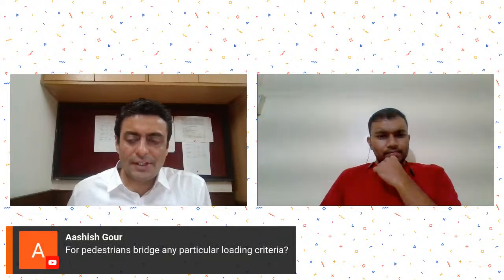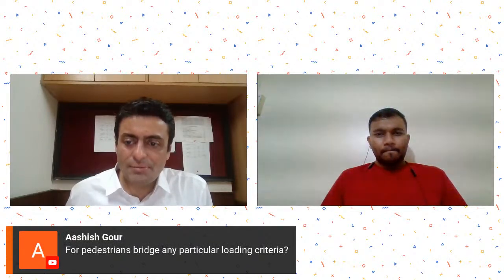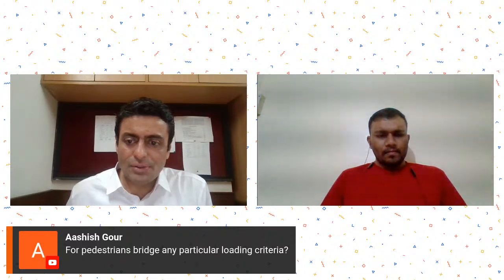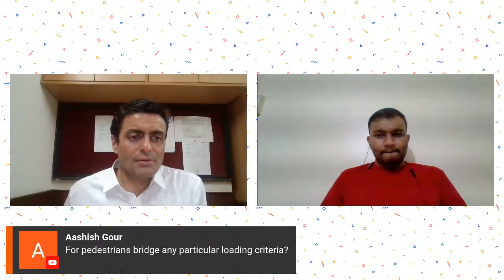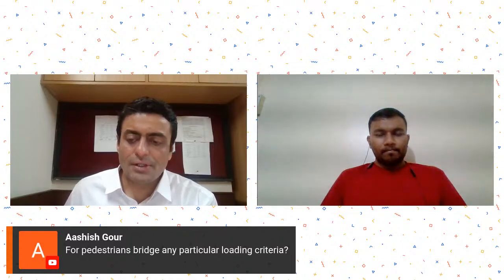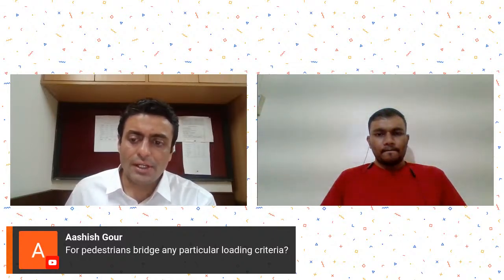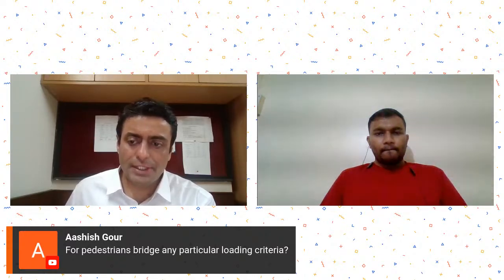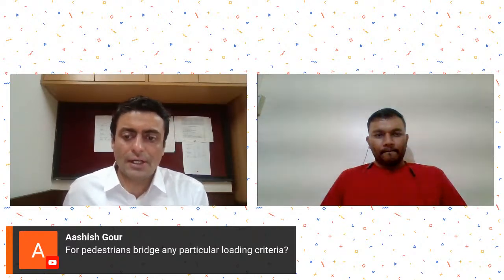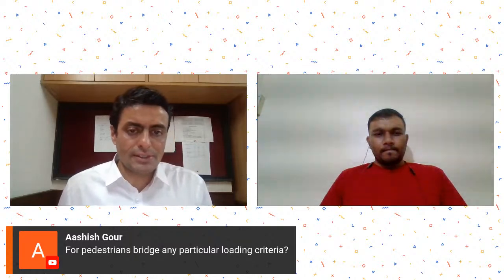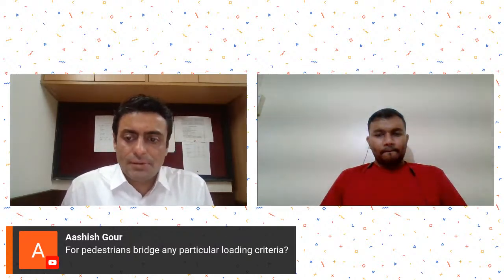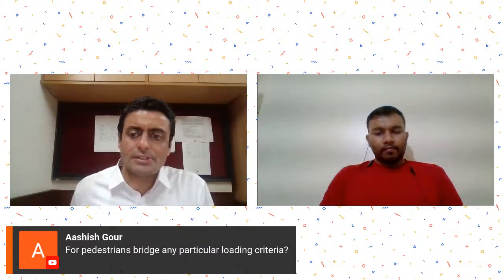Okay. Any other questions for Parth or me? You can put them in the comments. I will take a few questions that were left during our earlier discussion. Ashish ji was asking, for a pedestrian bridge, is there any particular loading criteria? If you are doing a pedestrian bridge, there is IRC SP 56, a special publication of IRC. You can refer to that, or the standard loading criteria that you get from IRC 6.